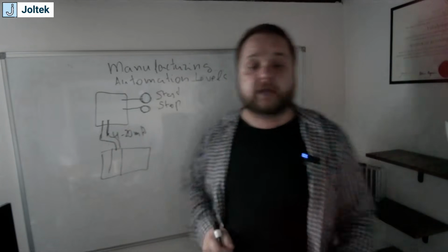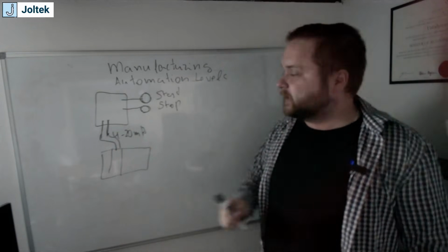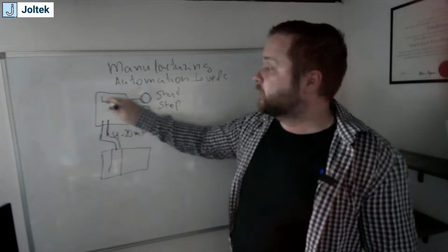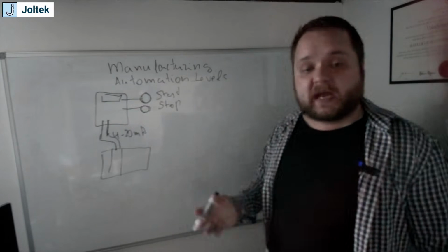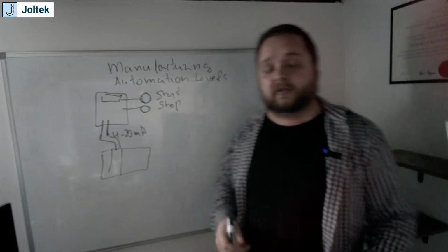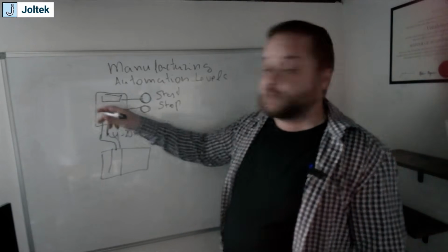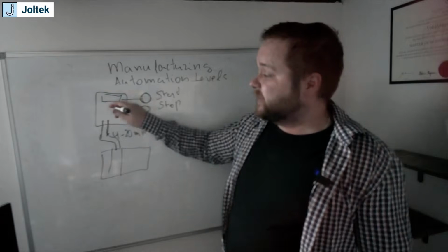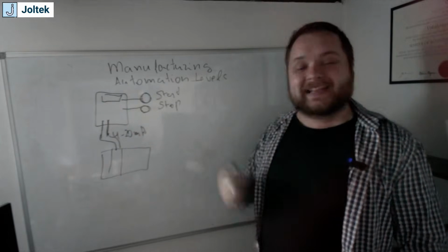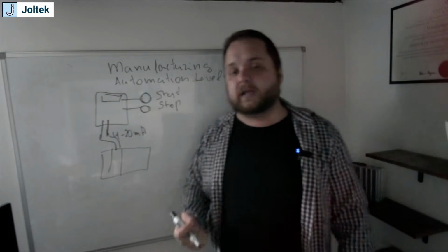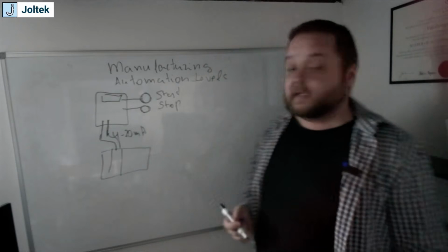It's going to start and stop your device. Once again, if this VFD fails for a variety of reasons, and those could be mechanical, it could be electrical, it could be a failure of the encoder, it could also be voltage problems coming in, this VFD is not going to be able to send a signal over the current line for you to know why it has failed, right?